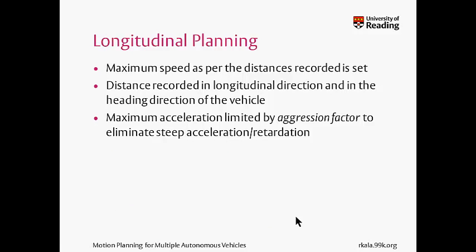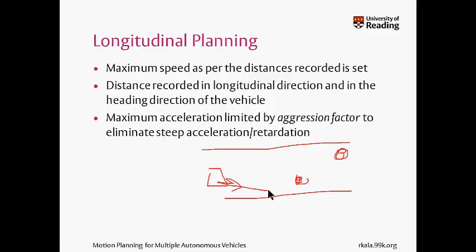But so far I have only played with the steering and I have not played with speed. Now speed, even in these kinds of scenarios, plays a very important role. If you leave your vehicle at a very high constant speed and there is an obstacle out here, it'll go zoom, it'll try to avoid this obstacle, and it'll either bump out over here, or it'll automatically try to avoid this obstacle and it'll bump out over here. So the problem was that I had to reduce my speed out here.